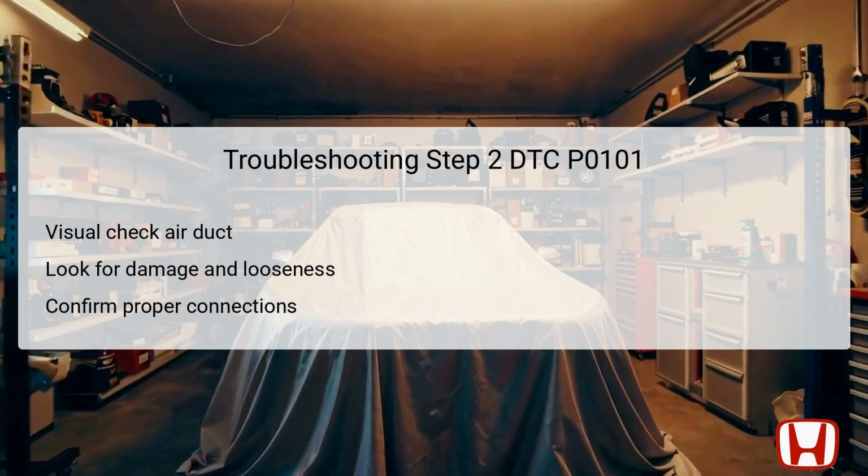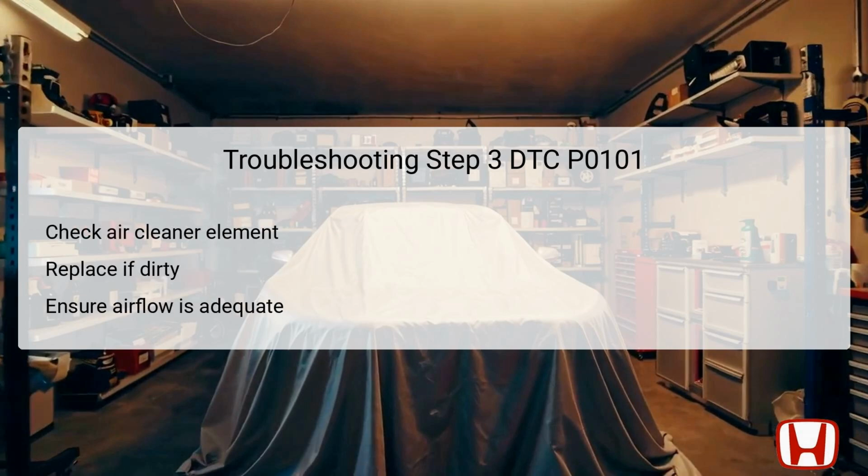If the duct is found to be in good condition, you can progress to the next diagnostic step. Otherwise, any damage should be addressed by reconnecting properly or replacing the duct if necessary, ensuring that air can flow freely to the engine. During the third troubleshooting step, it is crucial to check the air cleaner element for cleanliness.